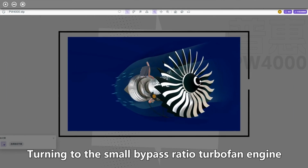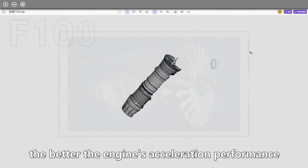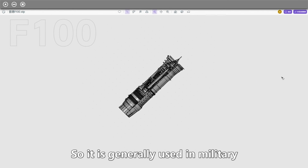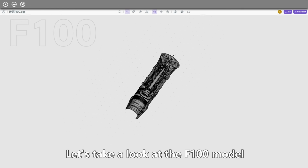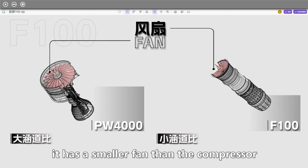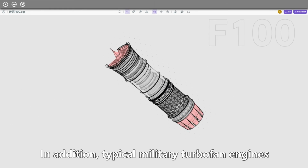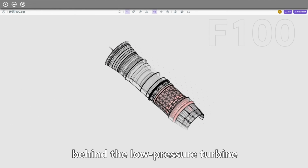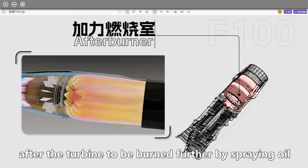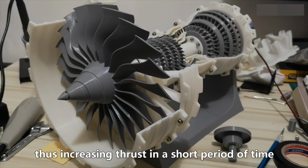Turning to small bypass ratio turbofan engines. The smaller the bypass ratio, the better the engine's acceleration performance and the lower the flight resistance, so it's generally used in the military. What does it look like? Let's take a look at the F100 model. Obviously, compared to the PW4000, it has a smaller fan than the compressor, which means a smaller bypass ratio. In addition, typical military turbofan engines like the F100 usually have an afterburner behind the low-pressure turbine, which allows the mixture after the turbine to be burned further by spraying oil, thus increasing thrust in a short period of time.